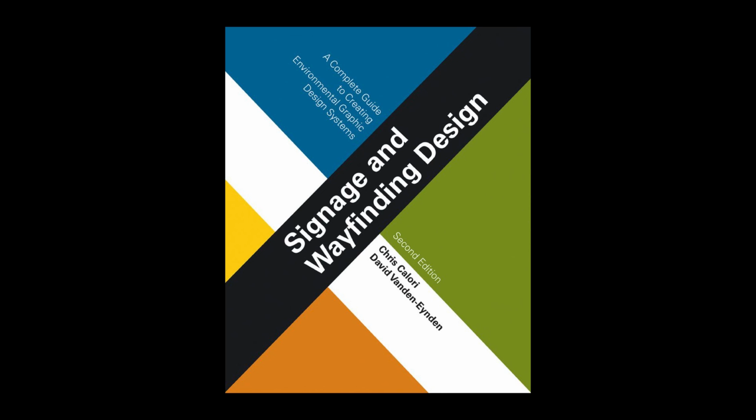The resulting aluminum oxide coating is effectively clear, although slightly cloudy, making clear anodized aluminum slightly less shiny than unanodized aluminum. Anodized aluminum can be colored in bright or subtle tones using various dyes, and relatively new processes allow full-color photographic quality images to be integral to a clear anodizing coating.